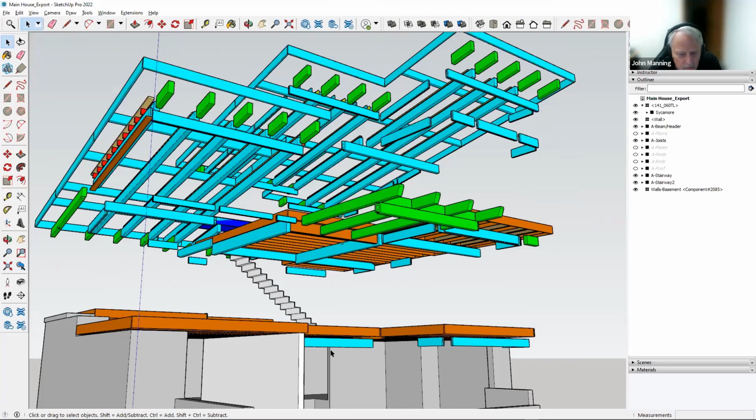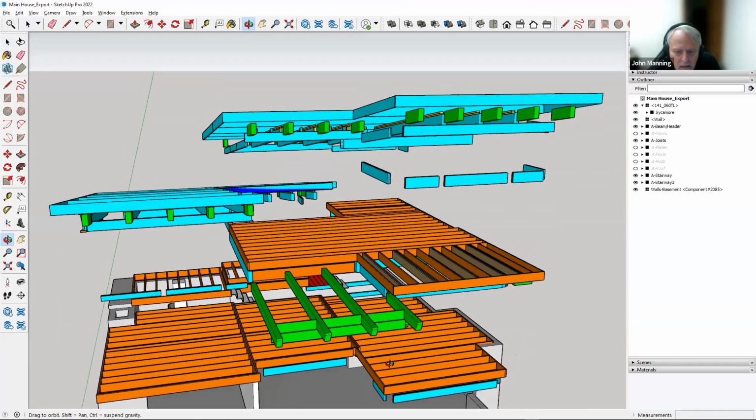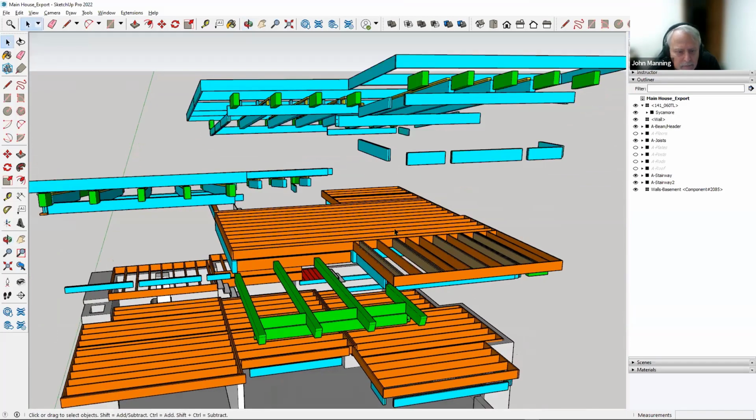So we're down at the lower level. I think the lower level and the first floor, based on having drop beams, should not be a problem from a ductwork standpoint. And let's talk about how we transition from a vertical riser to getting branch ducts down through the floor joists. That's where I'm struggling.